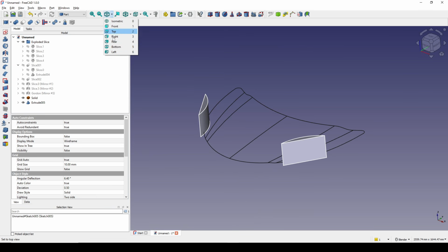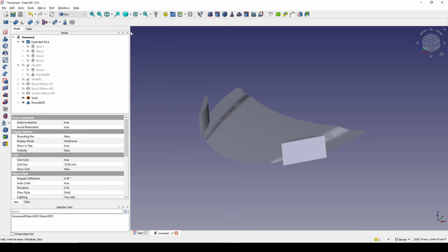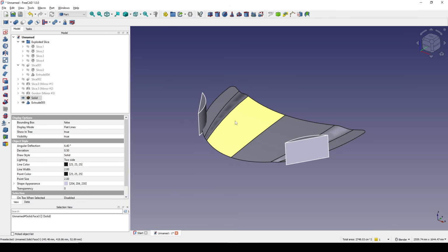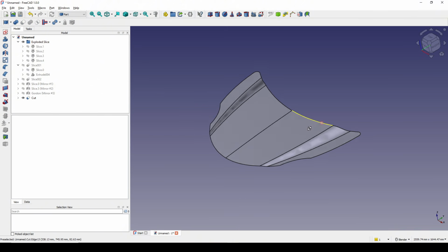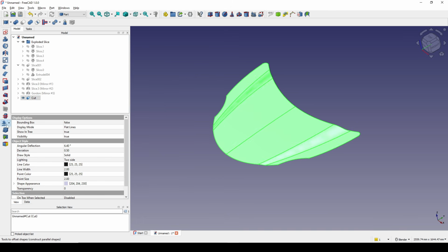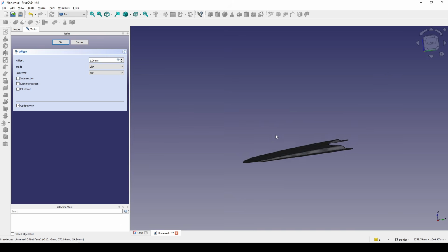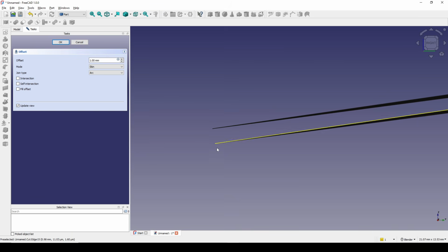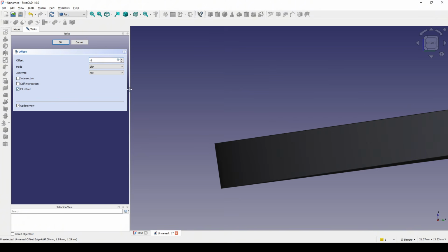Let me view the shade and the flat line. And I can select the surface and extrude and I go to cut. Right. Now I can select the cut and go to the 3D offset. Go to the right view and you can see the geometry goes up, so I don't want that. I set this to -3. Click on view offset, click OK.